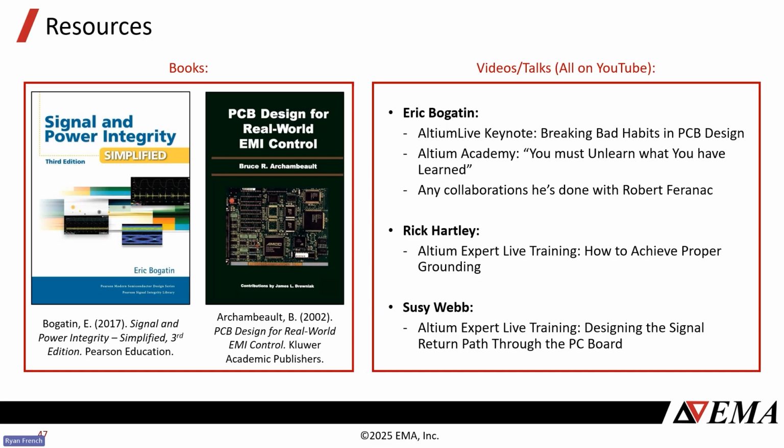One of the last things you do in a design is you put as many ground and power vias as you can in your board to eliminate those resonances. But just in case you're not fully constraining those fields, what you do is you put via rings around the outside of your board. You'll see this sometimes. It's usually just ground vias spaced evenly around the edge of your board, just so that if any waves do get to the edge of that board, they'll be reflected back in. So yeah, ground rings, any kind of ground, don't leave it floating. Make sure it's tied at least with one via somewhere.